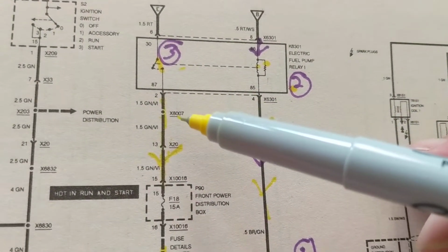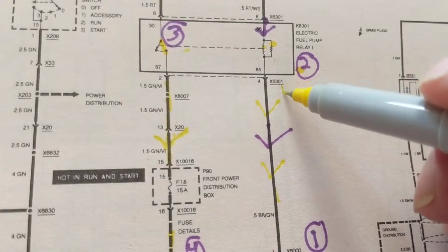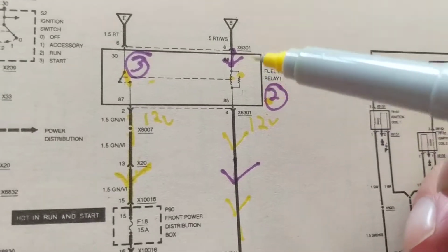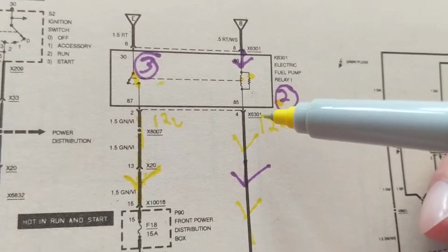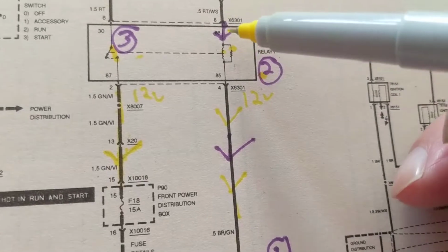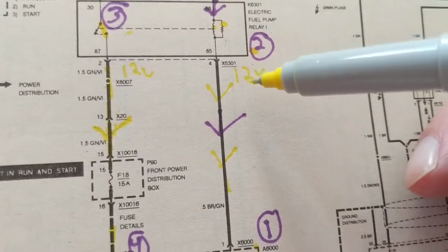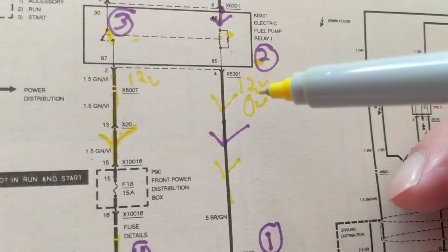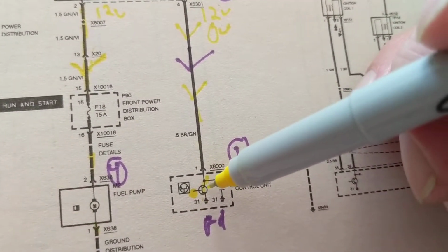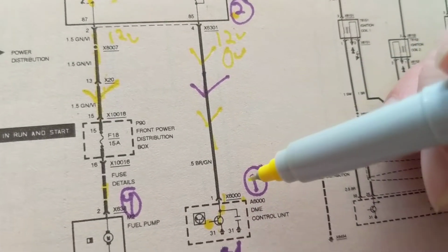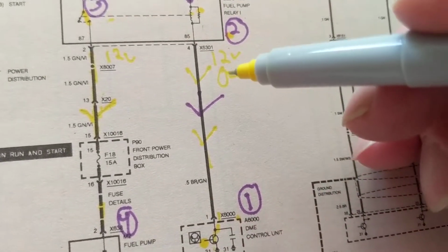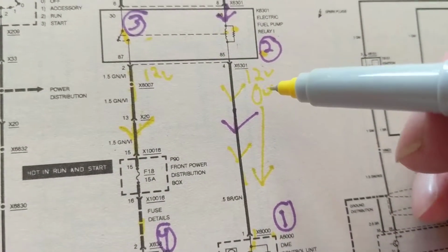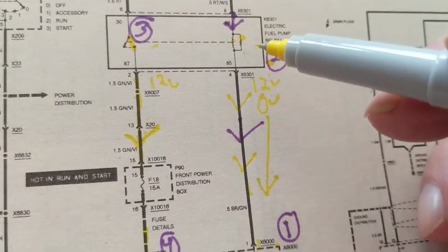If I want to troubleshoot, where am I going to put my probe? Everything is 12 volts. 12 volts here. This is 12 volts. How do I know this is 12 volts? This is connected to the battery, which is 12 volts. It's going to be 12 volts if it's not operating. When it's operating, this is going to be 0 volts. Right? So when this is grounded, the transistor is like a short circuit. The ground, it'll measure maybe 0.2 volts, something like that. We can consider it ground potential, and it'll be at 0 volts. If it's not, it'll be 12 volts.